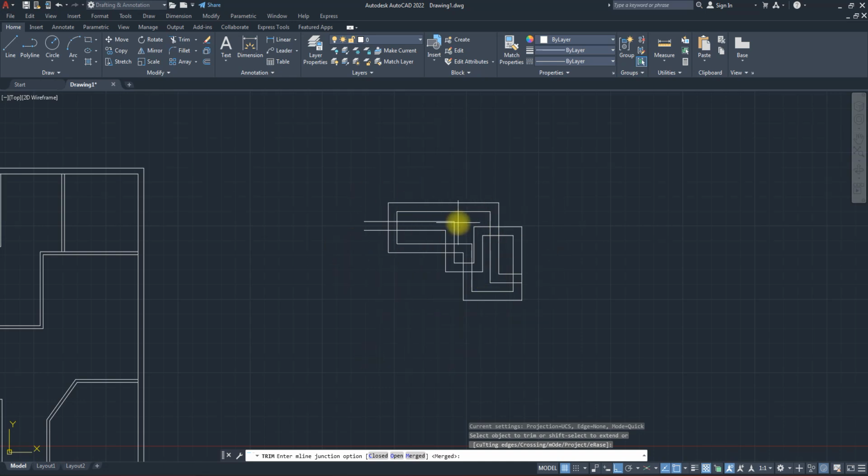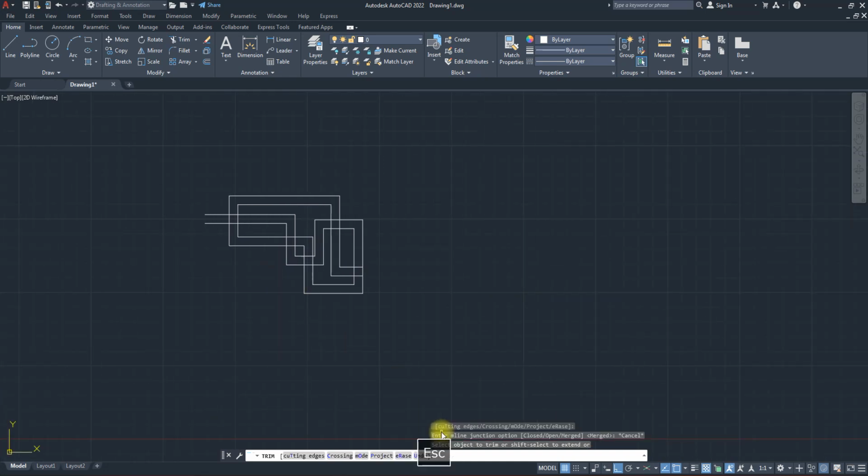on multi-line. It has its own edit tool. Multi-line has its own edit tool. So you have to run that edit tool for you to edit your multi-line. Okay. So for us to do that, you also need to know the shortcut. ML edit is the shortcut. Multi-line edit.